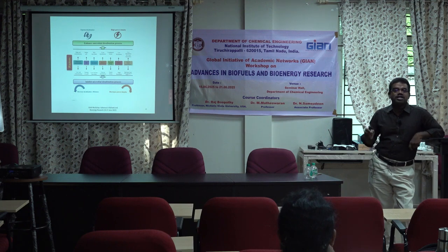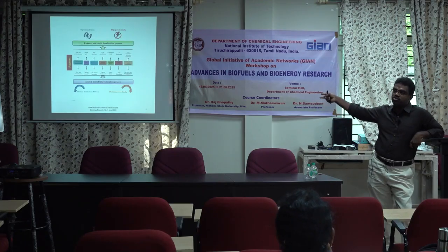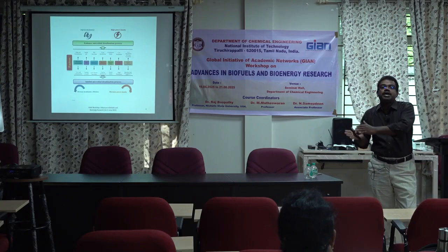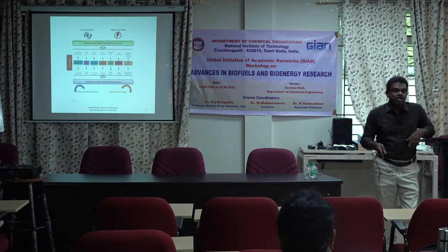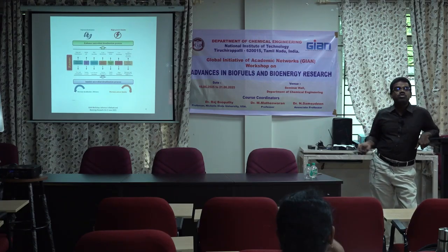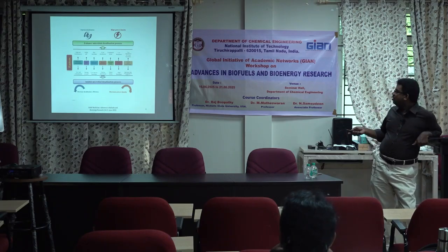As I told you earlier, there will be a concentration driving force between each chamber, from the anode to the desalination chamber, and similarly from the desalination chamber to the cathode chamber. Accordingly, based on that only, your ion transfer happens from one side to the other side. So, the concentration of the saline water will be the most significant as compared to any other factors.